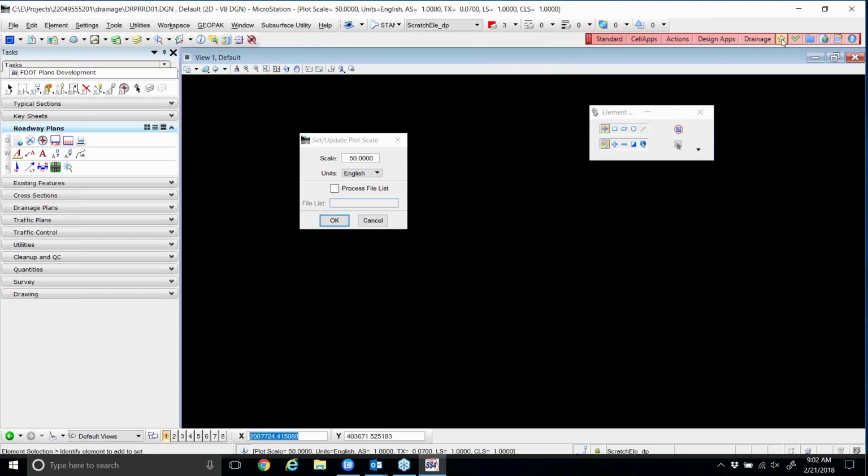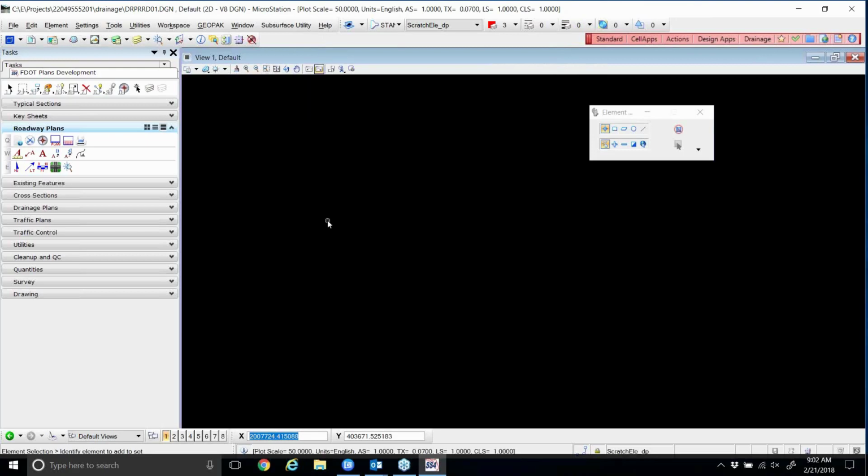And you'll probably, even though we're doing the open roads and other stuff now and using annotation scale, you're probably going to need to set that plot scale still, because some items are getting their size and scale from the plot scale of the drawing. Some are getting it from the annotation scale, and there's probably some other ways things are getting their sizing in the drawings. Not everything is based on the annotation scale right now.